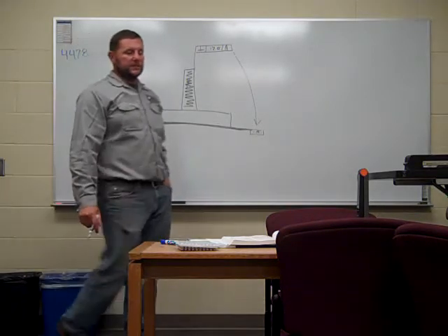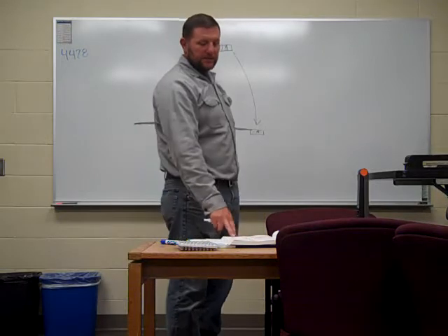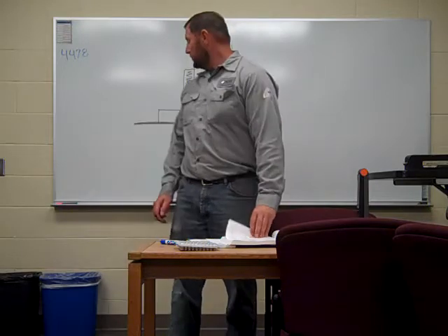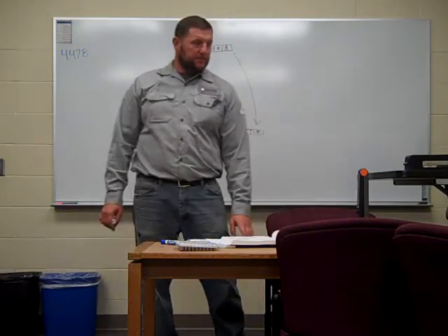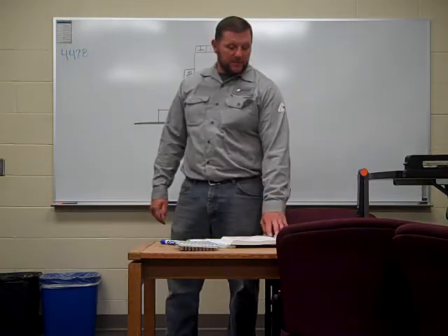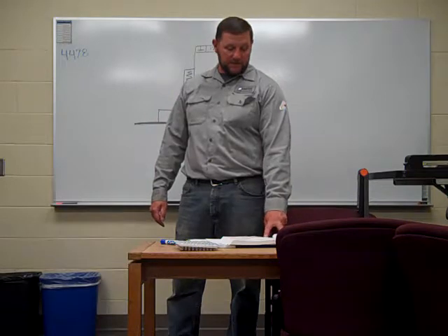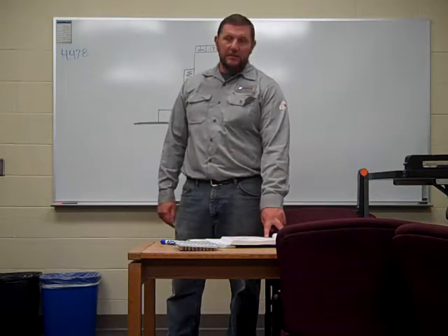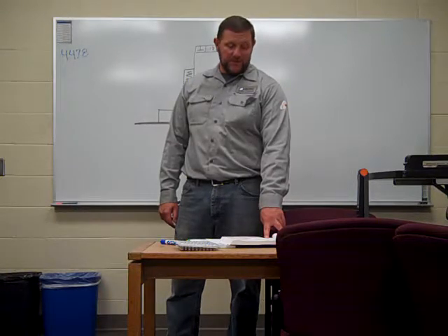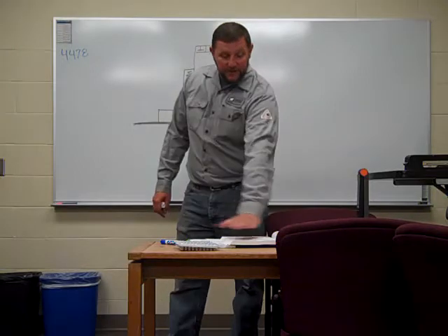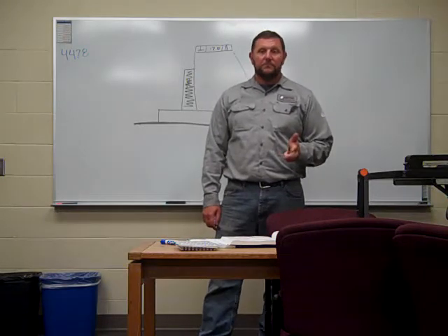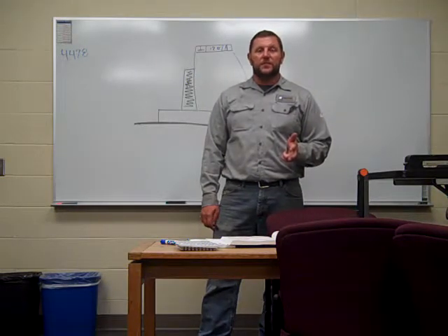And as you go through the book, as you see on page 125 on the right hand, there's a ton of symbols. We're not going to use all the symbols. Most of this stuff relates to a machinist. As we start going through this, on pages 126 and 127, you see figures 9-26 and 9-28. These are typically the symbols that we're going to be using. They kind of explain themselves, like straightness, keeping it straight, flatness. Usually perpendicularity and parallelism are going to be probably the primary two that you're going to be using.